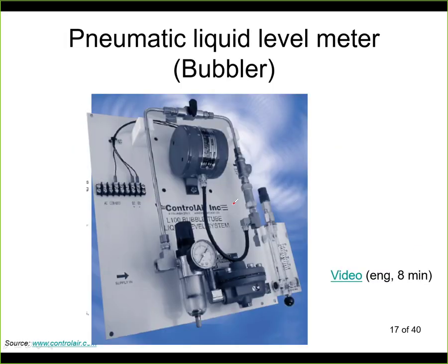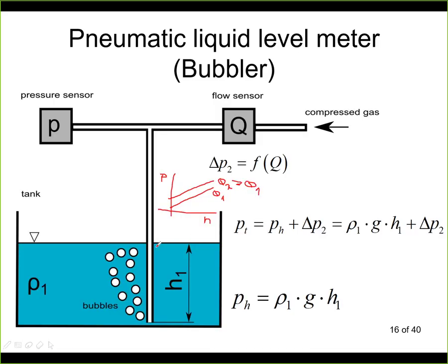So this can be used very successfully in applications where you have corrosive liquids, where you have sediments. On the other hand, it's not very suitable for applications where you cannot blow this gas into the tank. For example, let's say this would be a tank with beer, and you want to measure how much beer you have in the tank, and by blowing the air you would destroy the product. So the customer would not be very happy about this. So again, it's not suitable for all applications, as all sensors.